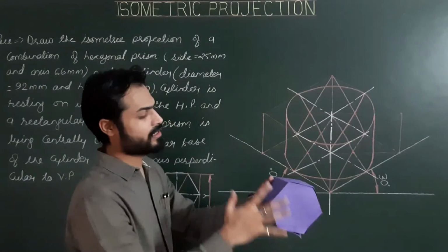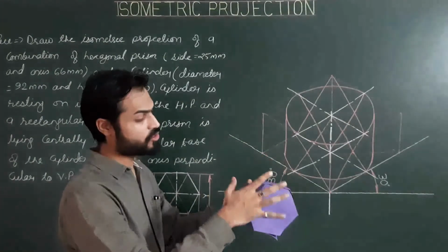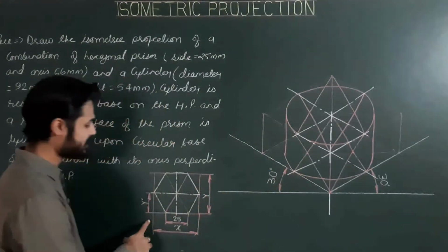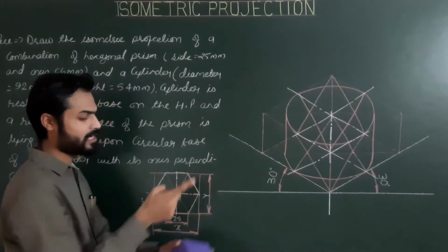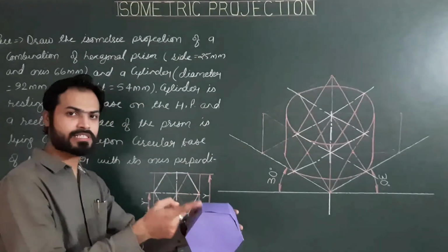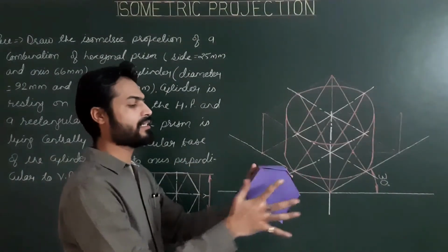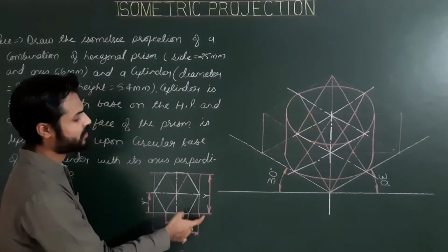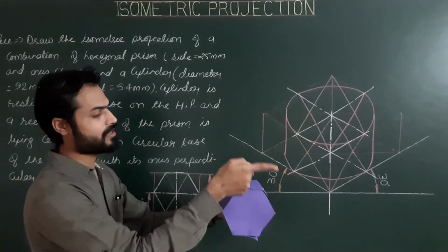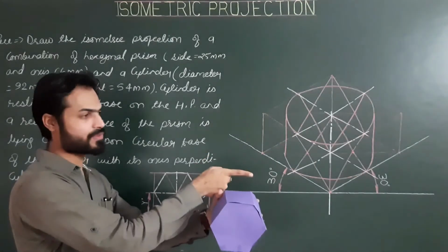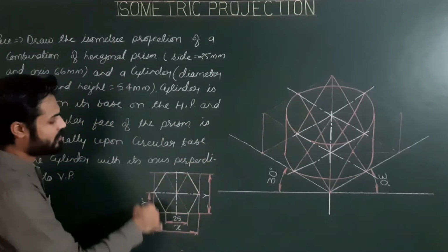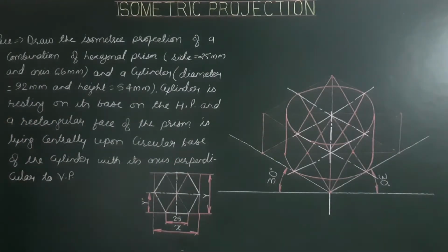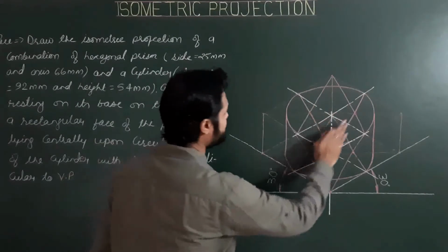Okay. Now if we assume that this hexagonal face is a part of this rectangle, then we can also assume that the hexagonal prism is also a part of a helping cuboid of size x by y by 66, because the axis is 66. So we can assume that this hexagonal prism is a part of a cuboid of size x by y by the length of the axis. And now we are going to project that cuboid first on the upper circular base.